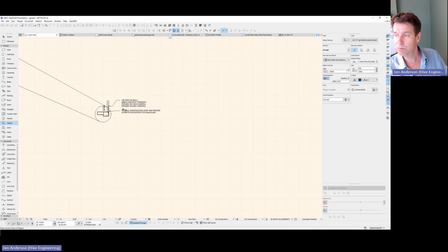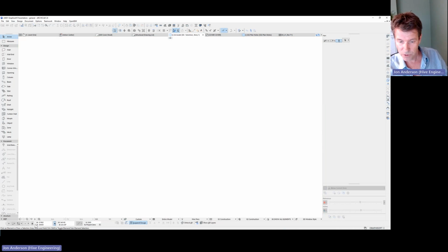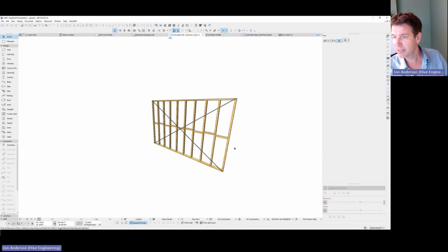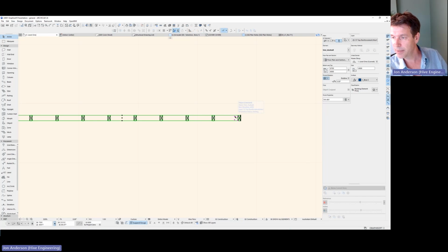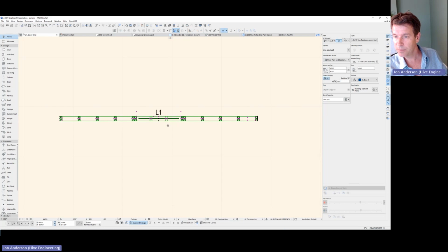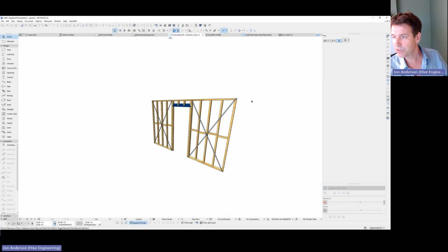I use some smart tools for doing walls, like internal stud walls and that type of thing. And then in those, I'll show you quickly one of those. So that's a sort of smart stud wall, like that. But into that, again, you can use the hotspot editing, and this is a good example where you might be able to grab an element and then go, I'm going to put some door openings into it, and then there's a lintel built straight into it,